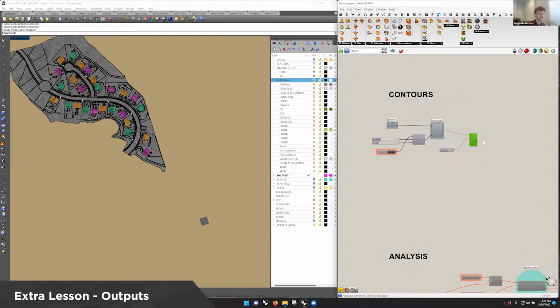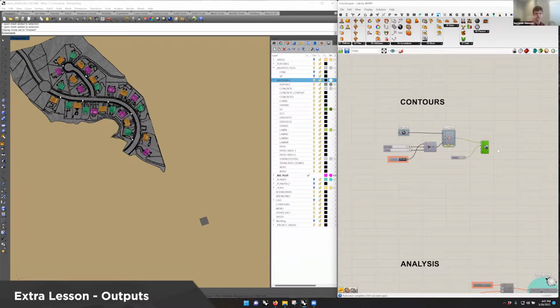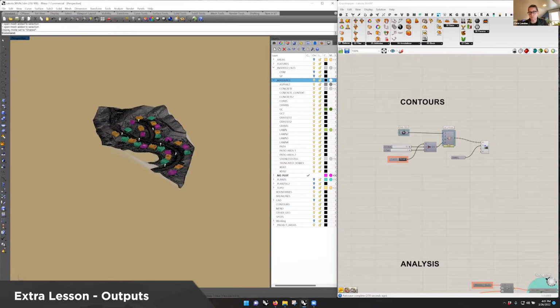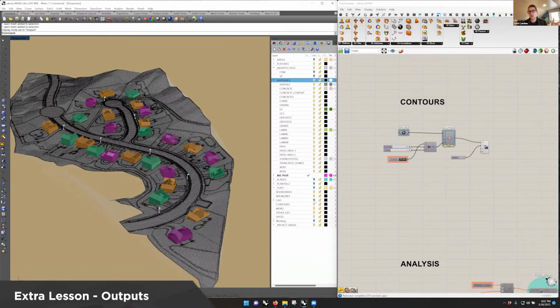Yeah, that's not specific to Topo Kit or anything. That's really anything that you're working with in Grasshopper, having it closer to the origin. It's a good practice in any 3D modeling software, to be honest. Rhino, Revit, SketchUp, whatever. Just keep it closer to the origin.